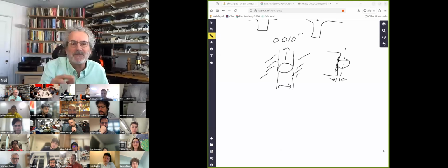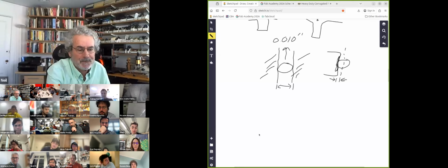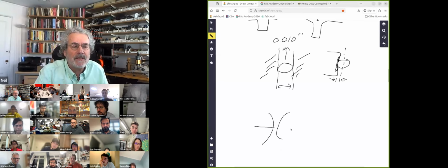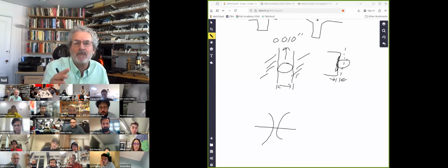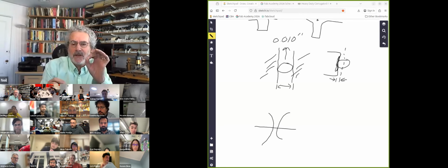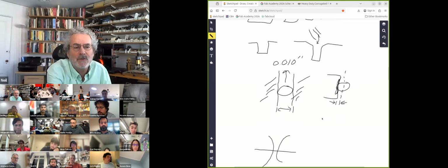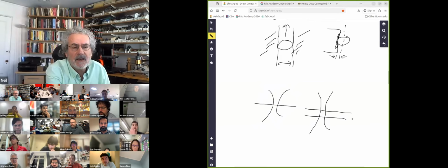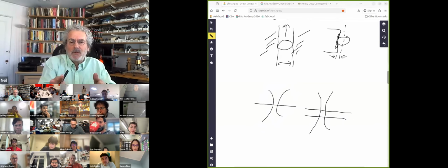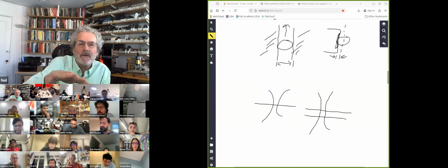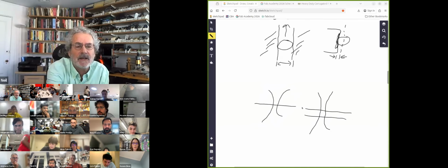Got it. Two notes on that. The first one is, as Debu showed, there's what's called the beam waist. Typically, you want that at the top of the material. However, in some cases you intentionally defocus, because you can get artifacts if the beam is too skinny. Now, to your question, if you look at this beam waist versus the material thickness, for many applications the variation between the top and bottom isn't that large. And so you focus at the top and it's okay. However, when you're doing deep embossing, that's not true.